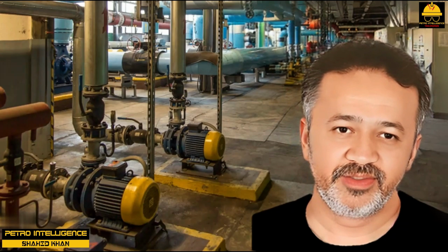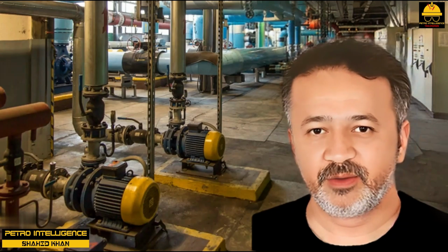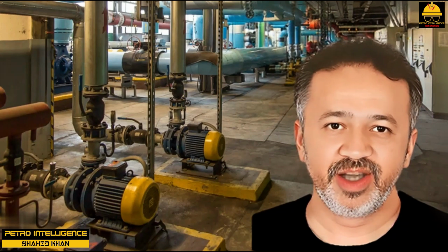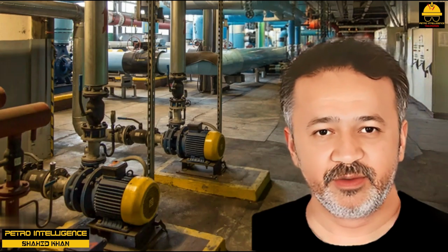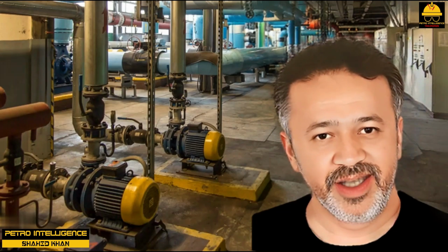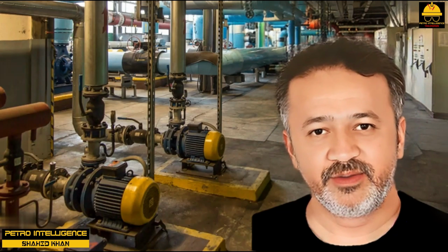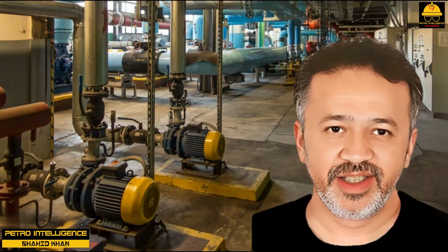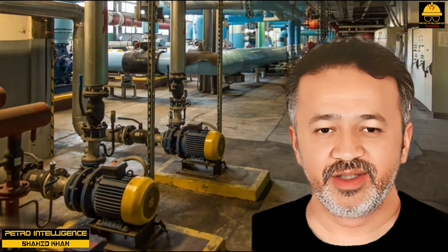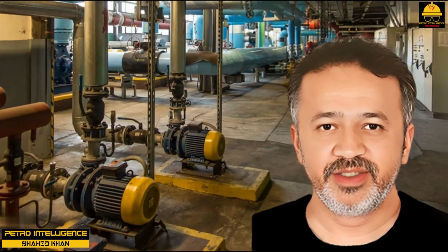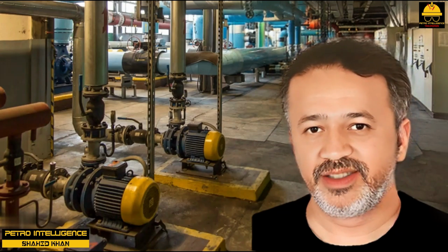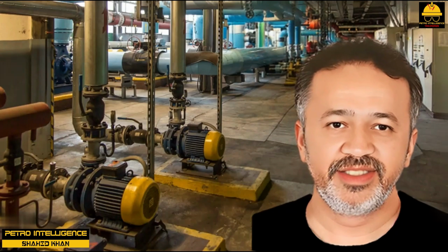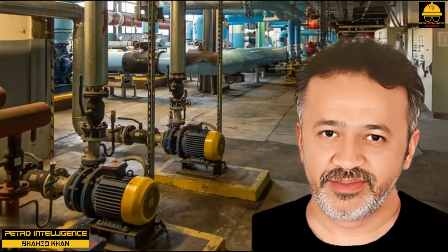I once increased the flow through a crude tower bottom pump by pushing hard against the base of the governor and forced it to actually open to its maximum position. The pump speed came up 300 RPM, and the flow increased by about 15%. Another possibility is to open the speed or hand valves, as described in the lecture on steam turbines. This will introduce more steam into the turbine case and slightly lower the pressure in the steam chest.